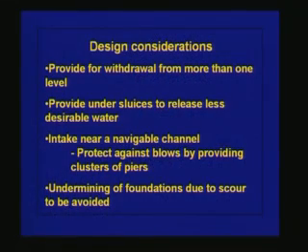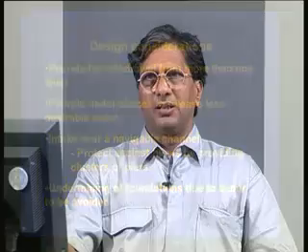Undermining of foundations due to scour should be avoided. This is very, very important, because if we have located the intake structure inside the river, like the first intake structure that I have shown, then during floods the velocity is very high and the sediment sitting on the bed can get scoured.